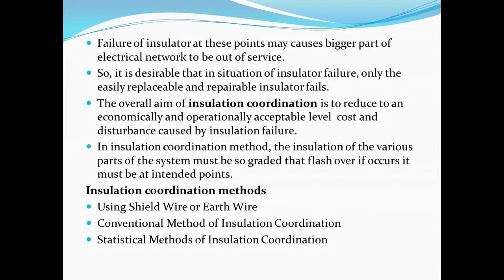In this insulation coordination method, the insulation of various parts of the system must be graded, so that a flashover, if it occurs, is at intended points. There are three methods of insulation coordination.